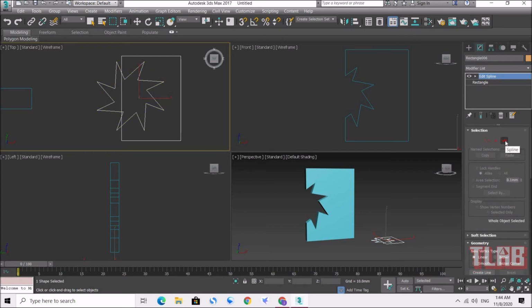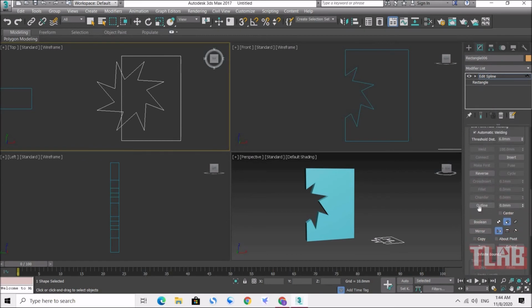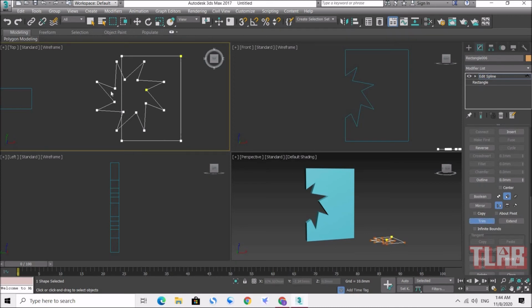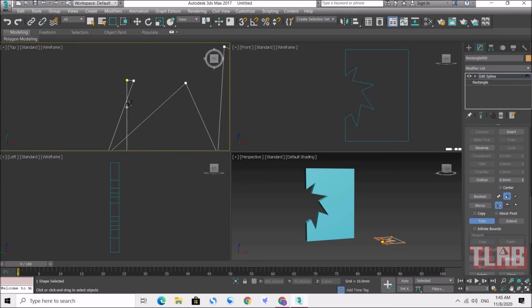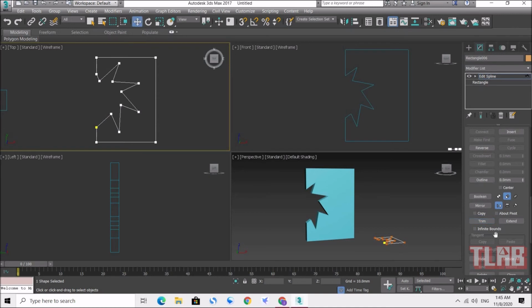Now next stage, you need to use Spline. Okay, after selecting Spline, then you move down, go to find the word Trim. Just click. And then after that, just click the outside parts, cut and cut. That's all. Then one more. Maybe this one you need to cut also. Like this. Okay, finish.